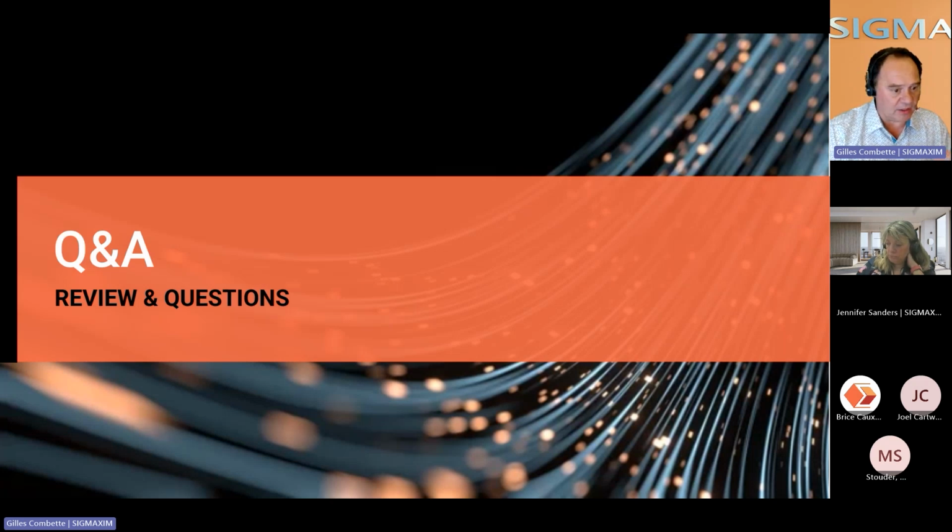Then you see what is not compliant, what will not work. And number 3, it could propose solutions to fix some items. I would give an example with the illustration we showed just before, the funky shape I was talking about. If you're moving from a laser, which has no problem machining those funky shapes, to punching, you've seen that we have a tool that helps make this conversion, to make this more punch friendly.